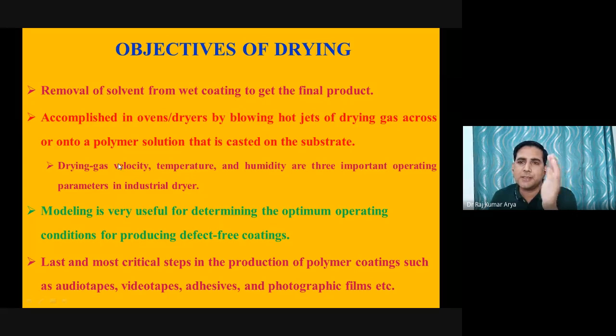in that case you will have some bubbly characteristic on the film. You don't want that, that is also a defect. Then moisture: in the case of painting your house in the rainy season, you will find the quality of the film once it is formed is very bad. It's only because it's not dried properly. It can absorb moisture from the atmosphere and your coating may fall down.